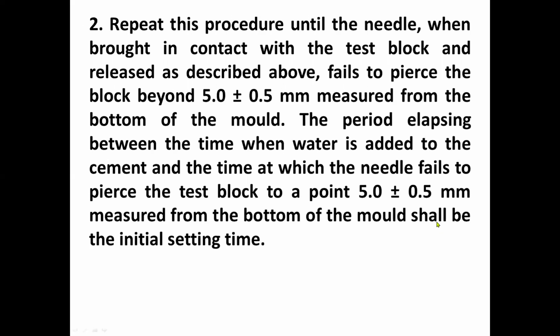For the second step, repeat this procedure until the needle, when brought in contact with the test block and released as described above, fails to pierce the block beyond 5.0 plus or minus 0.5 millimeter measured from the bottom of the mold. The period elapsing between the time when water is added to the cement and the time at which the needle fails to pierce the test block to a point of 5 plus or minus 0.5 millimeters measured from the bottom of the mold should be the initial setting time.